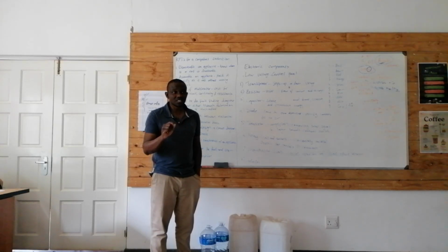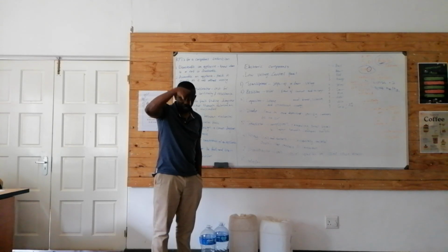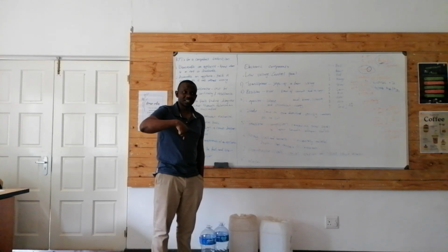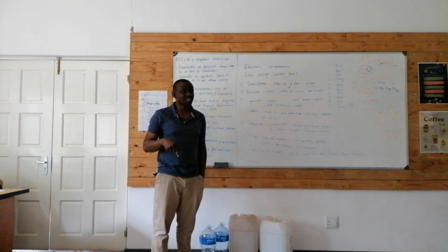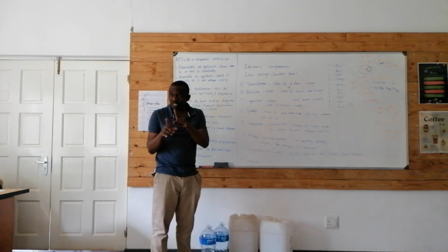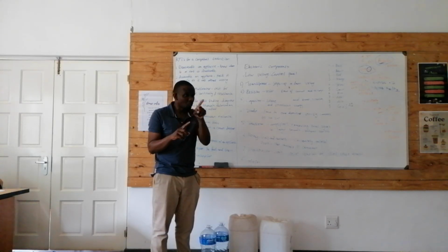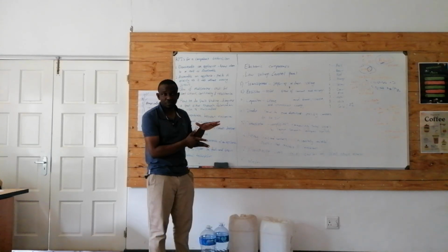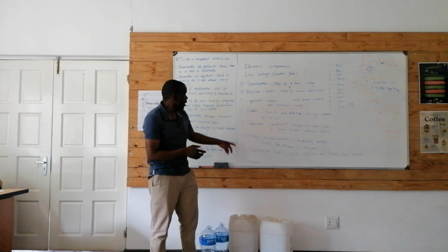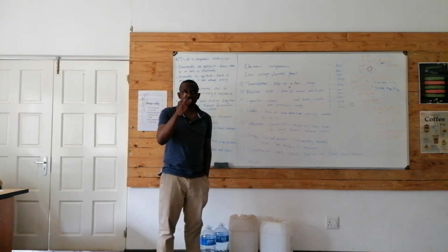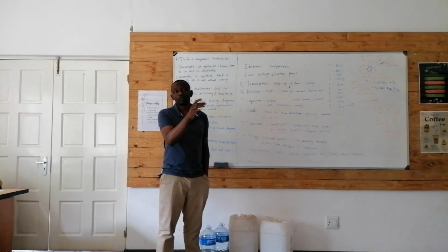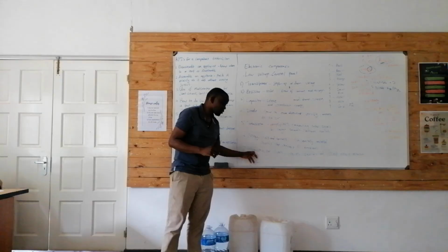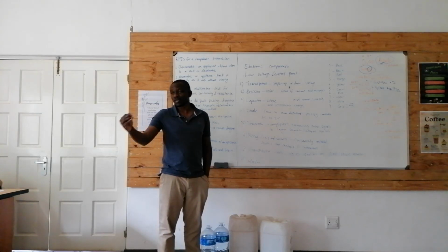But if you fail to see the damage, check the connections. Things that bring in the signal, are they bringing the current in? Are they bringing in the communication that's supposed to be executed? So there you need to check all the belts or wires that bring current into the PC board. Are all your components connected properly to the IC, the microprocessor? Remember, here I'm talking about appliances that have a microprocessor. Are they all connected?